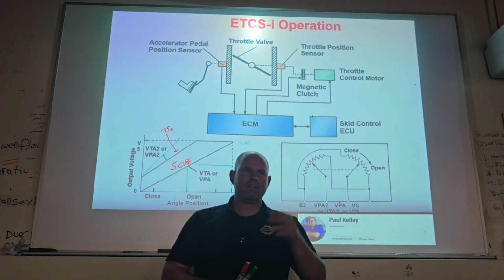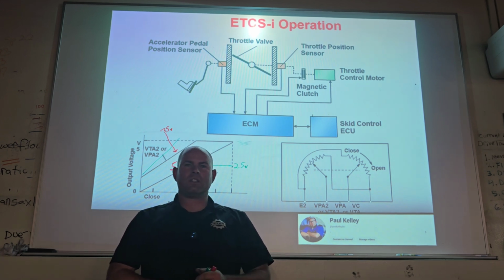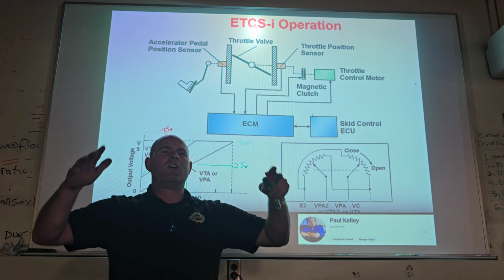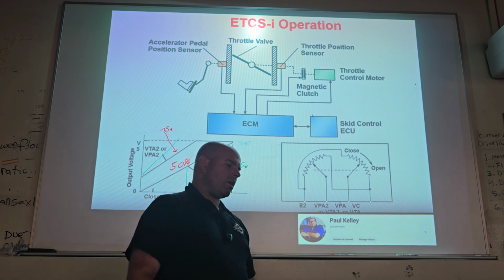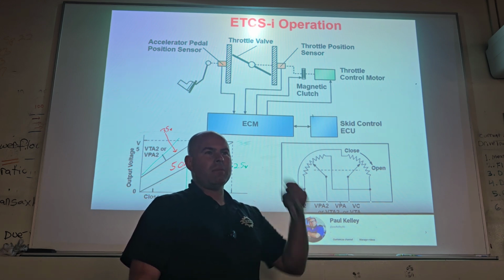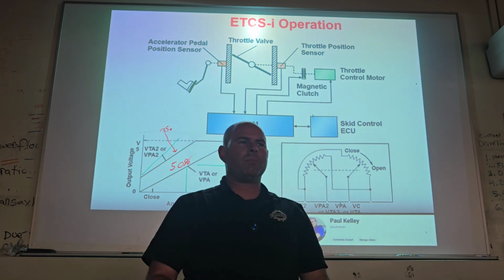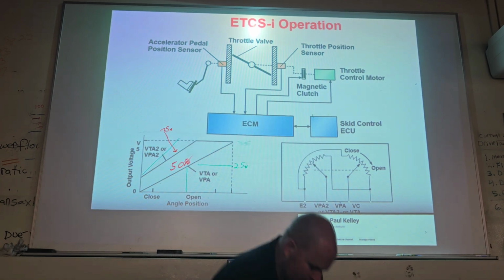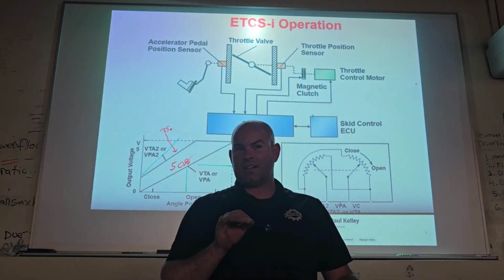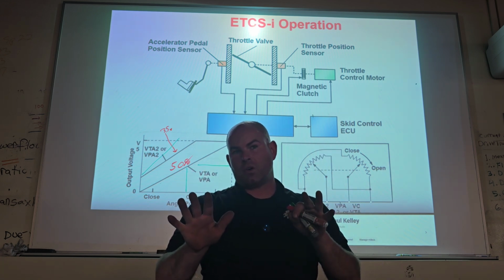You understand? 100%. A Pontiac Torrent, which is basically like an Equinox, came in. The customer said the car accelerates on its own. I'm like, yeah, hilarious, I'm watching the news, whatever. First, your job is to verify the concern. So I go to verify the concern. I punch the throttle, and it was scary. The throttle totally stuck. It was just going nuts. But in my mind, I'm like, there's got to be something mechanically wrong. So you know what my first step was? What would your first step be? Press the brake. This is where Toyota had a little bit of a dumb spot. If you pressed the brake, the ECM could see that you pressed the brake, but it would still let your throttle go. Okay, they reprogrammed that.